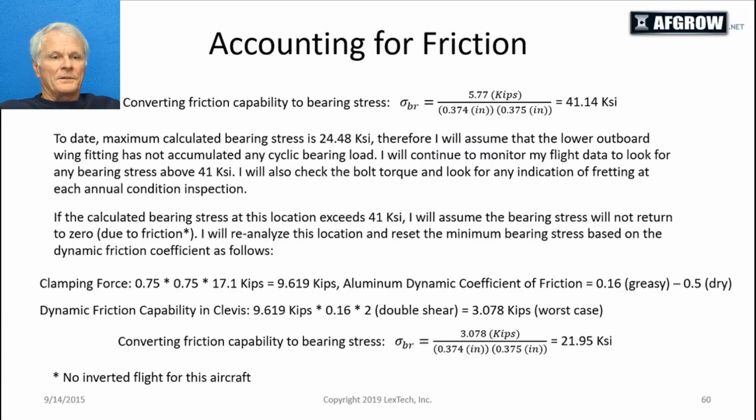And that works out to be 41.14 KSI, which is about double the stress I've seen in any one of those flights. So that indicates that so far that life prediction is probably way low. You'd have to do a test to verify that, but I felt very comfortable that the airplane is going to have a long life.